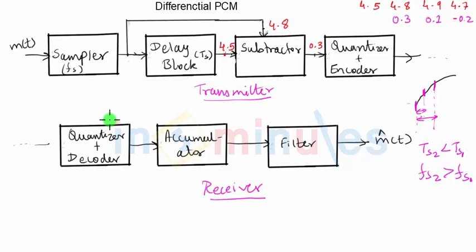What is this quantizer doing on the receiver side as the very first block? The input signal which is being received by the receiver, as we just now said, may not have the two predefined voltage levels. It might be corrupted due to the noise present in the channel. So I want my received signal to get its two original voltage levels back. In simple words, I want to assign two fixed voltage levels to my incoming signal once again.